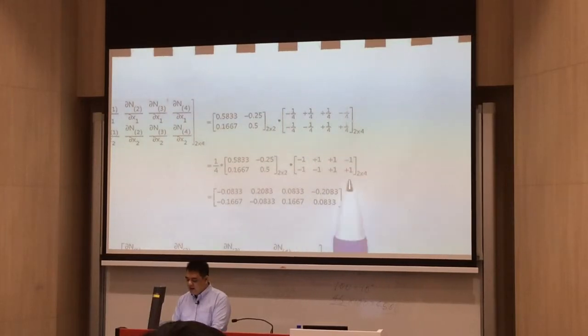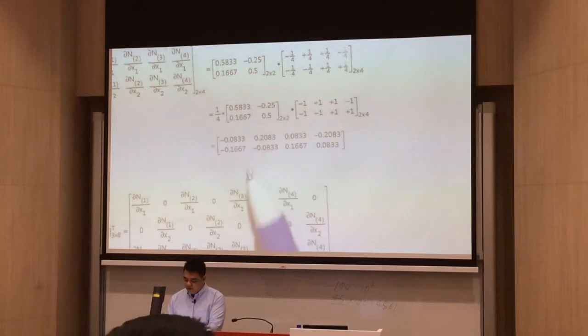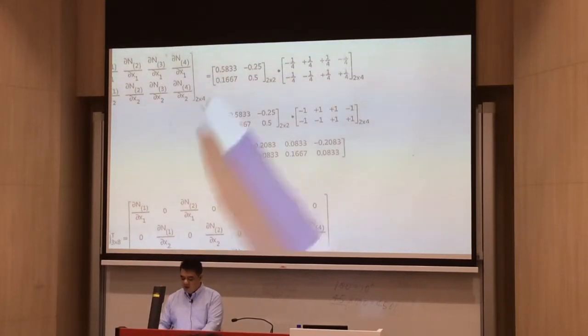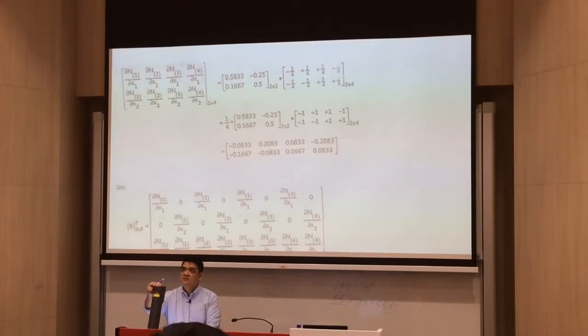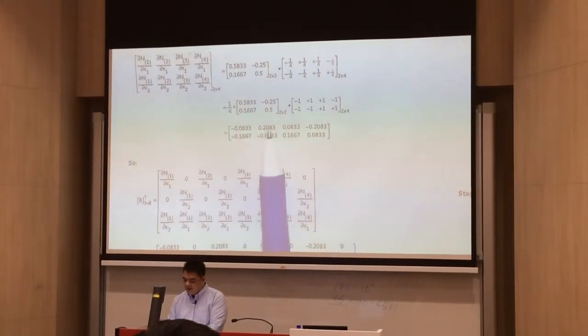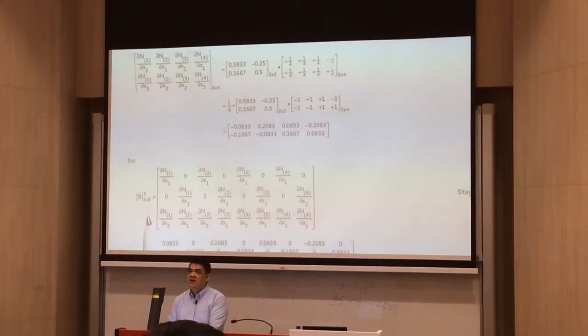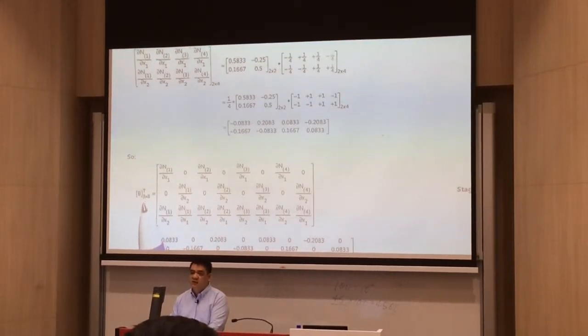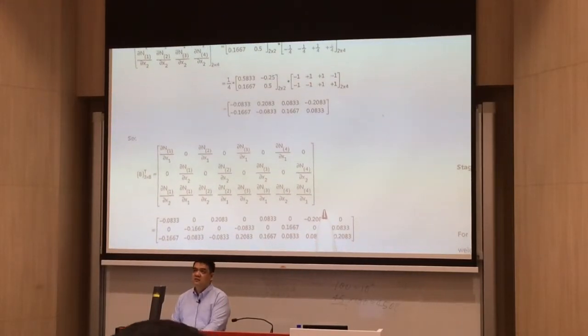Right? So simply perform matrix multiplication and you get these values. So once you get this one equal to that, this equal to that, you can complete now your strain displacement matrix transpose 3 by 8 using this matrix equation here.